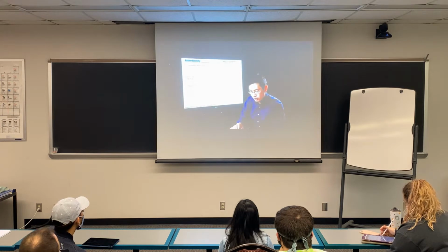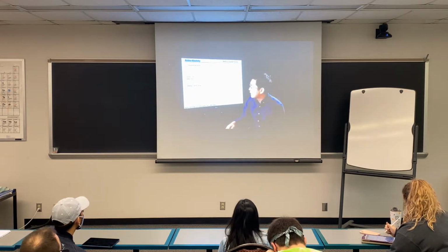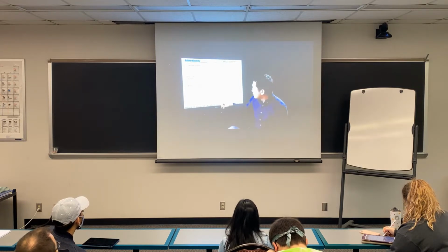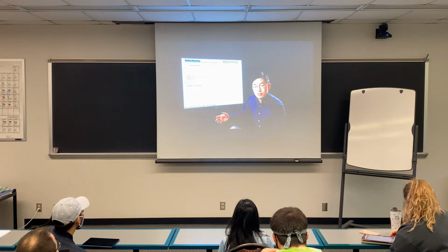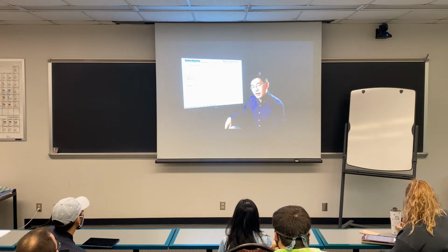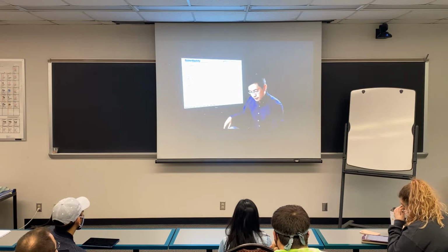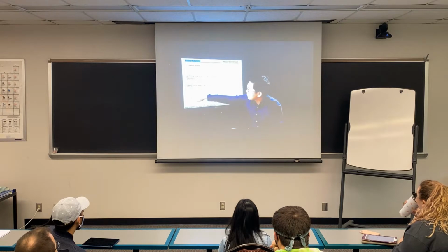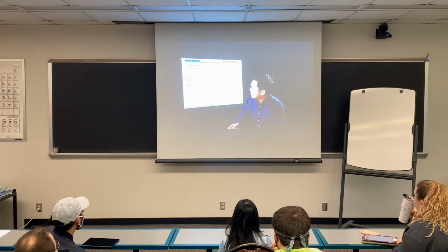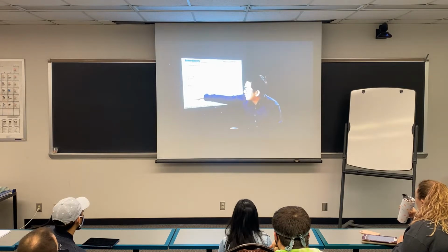So a smart way is to combine the conventional approach where we add, as well as adding two additional terms to this inverse Langevin function to capture those non-ideal Gaussian coil deformations. Okay, so this is basically what people showed in the probability distribution of chain function P dependence of n, x and h.